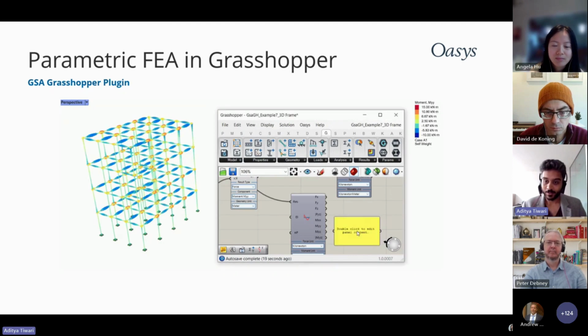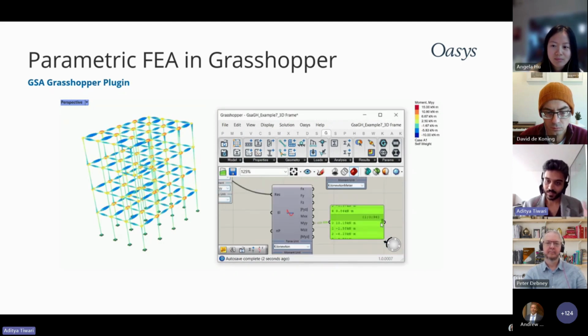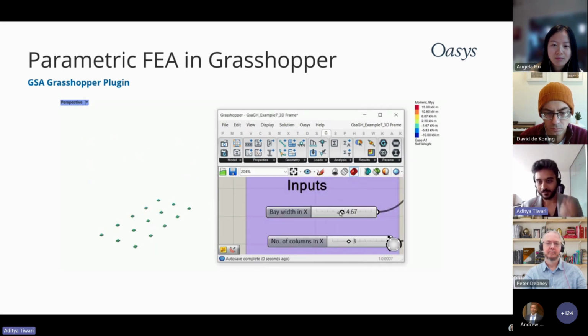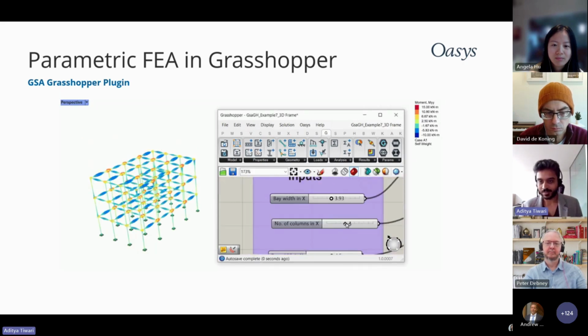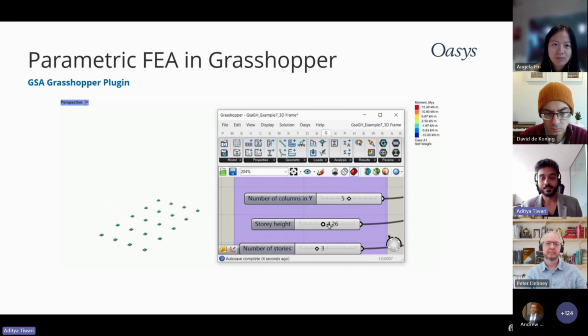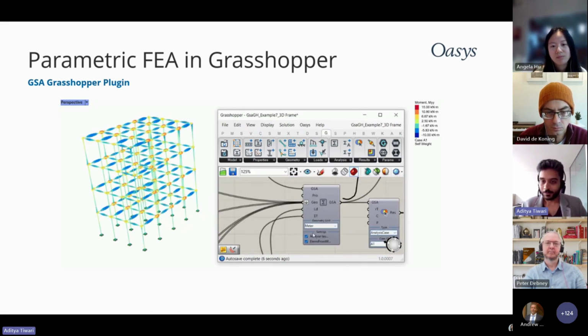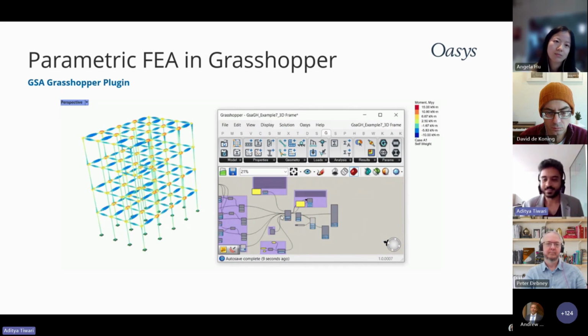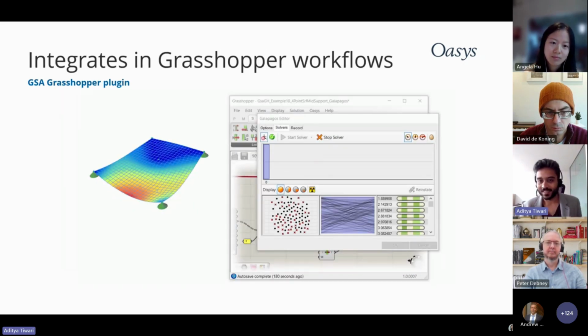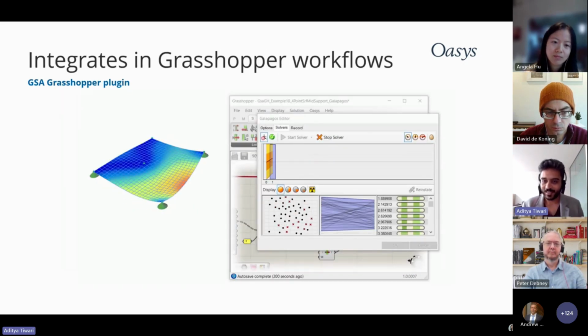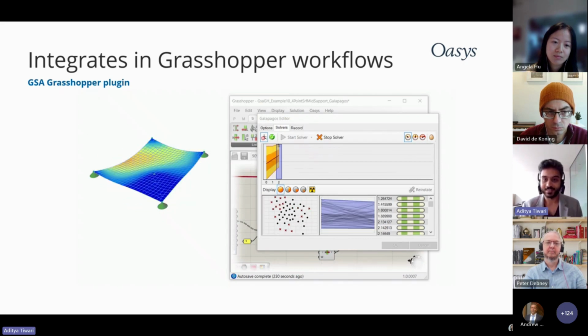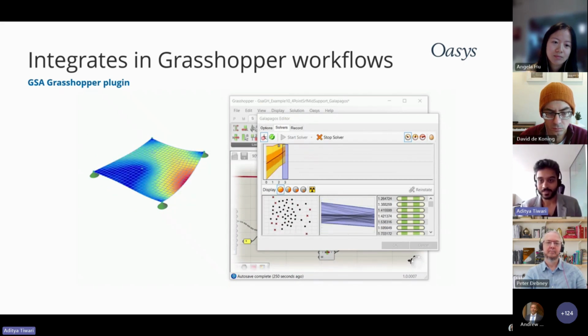This means that you can do everything, that is, start from building an analysis model, load it up, do an analysis, view the results, and do further post-processing all inside Grasshopper, because the solver is inside Grasshopper. A consequence of this is that all the usual suspects you might have, like does it integrate with form finding in Kangaroo? Yes, it does. Does it integrate with Galapagos optimization?